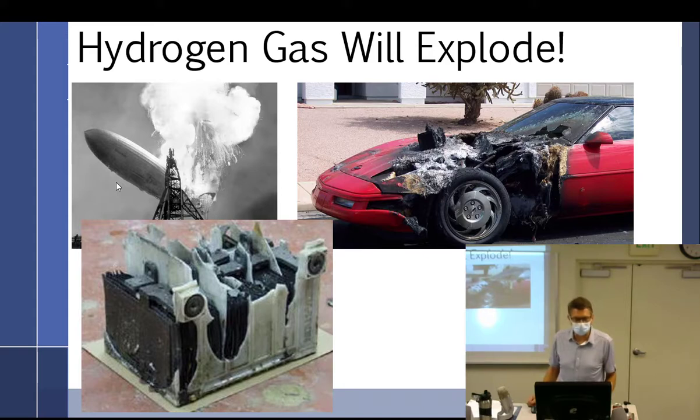It's kind of a controversy to this day, but it's believed that it was static electricity because in fabric-covered aircraft, you use aluminum pigmented paint. That's what they call dope, but it's aluminum crushed up into this paint, and you paint it on, so it gives it UV protection. Well, it's aluminum, so it's conductive. So there was a spark. The spark ignited the hydrogen, and right there on camera, the whole thing burnt, and everybody crashed and died. It lit up in like a second and a half. It was gone. That was crazy.